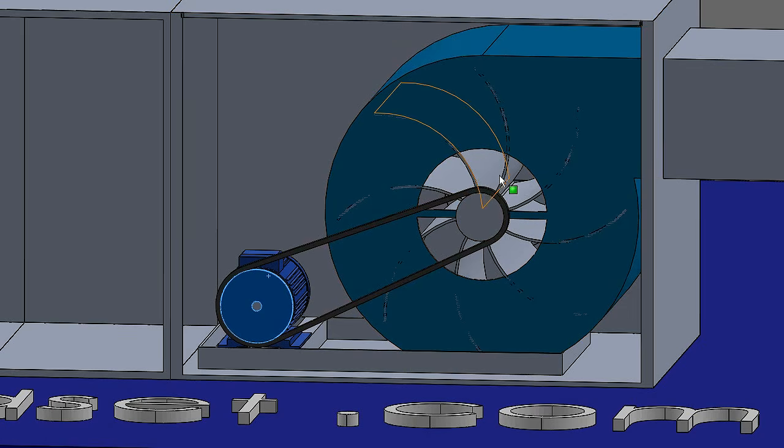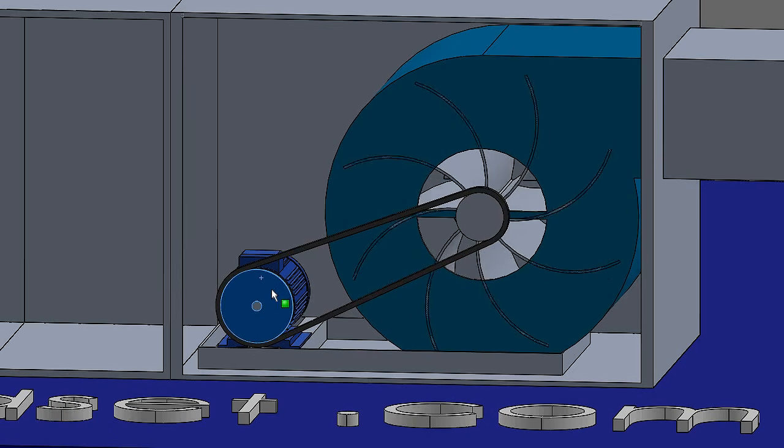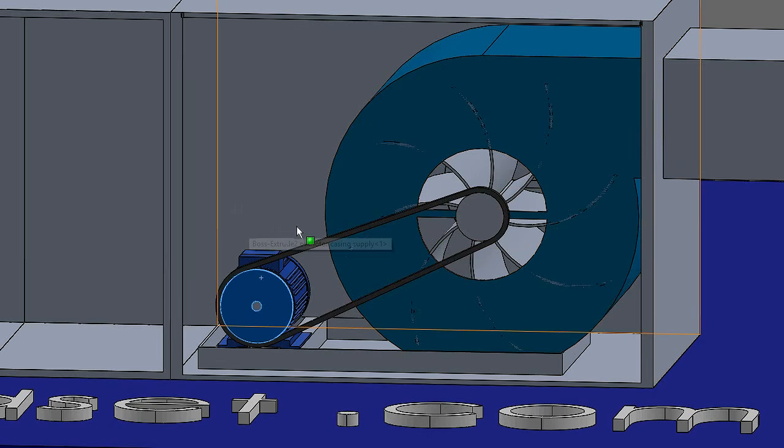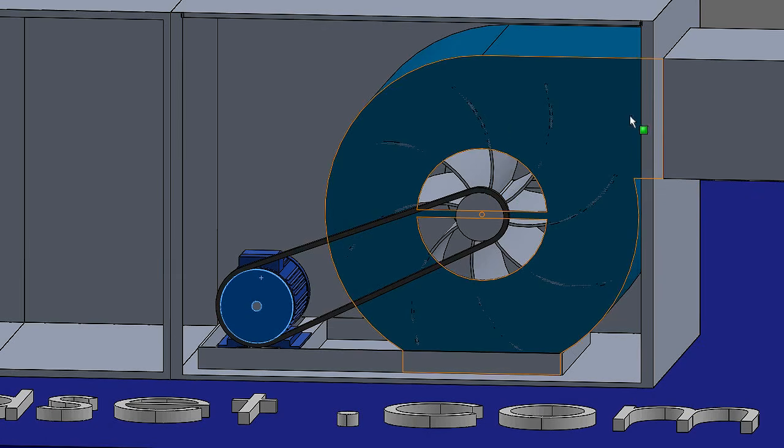So as this occurs, it's following along the curve and it's being shot off, and this is pushing it, and as that comes around to say here, it's at full swing, and it gets thrown out, and there's more air coming around this way. It's being pushed, as that builds up the pressure, the static pressure in this duct here, and that drives all that air out. So that pressure difference caused there, so this would be a negative pressure or a lower pressure, and then this will be a higher pressure because the air here is being compressed into this duct here, and this is being sucked in, so it's a lower pressure going in.